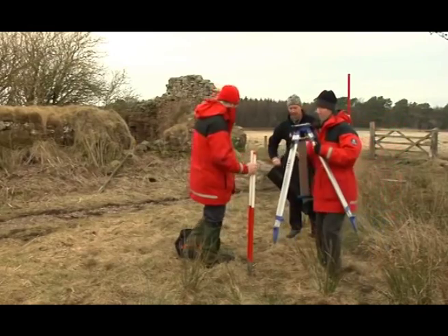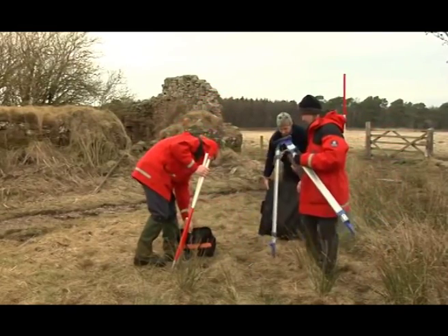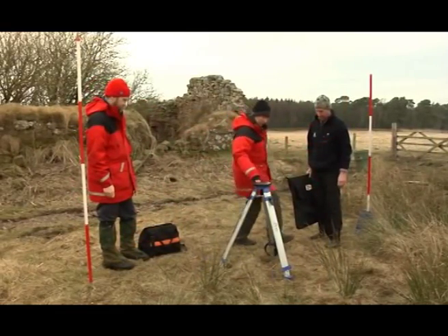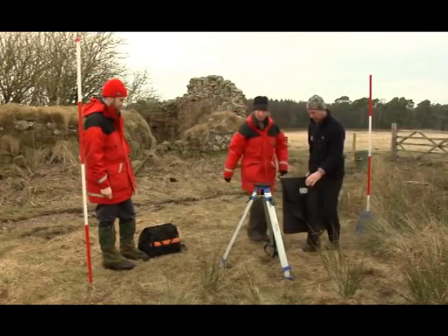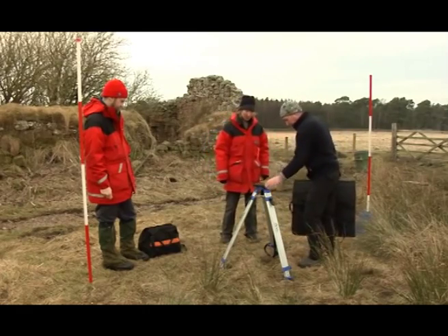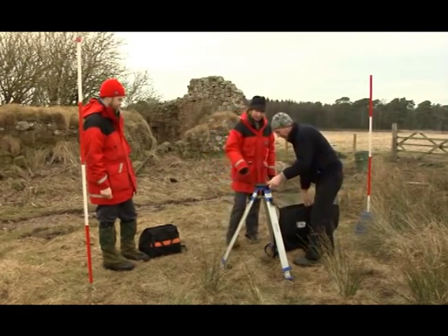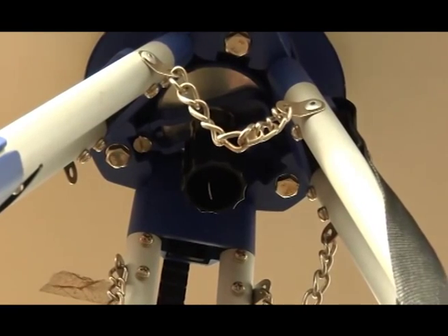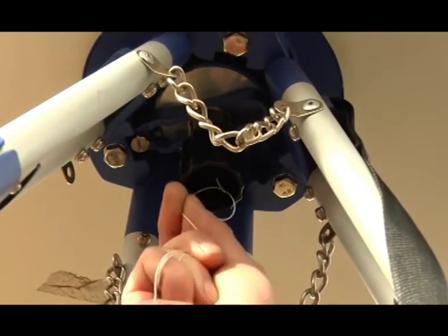Procedure: the surveyor goes into the field taking with him a map which is already drawn. His purpose is to find out the heights of vertical objects. He sets the plane table at some point and resects his position. The clinometer is placed upon the plane table.